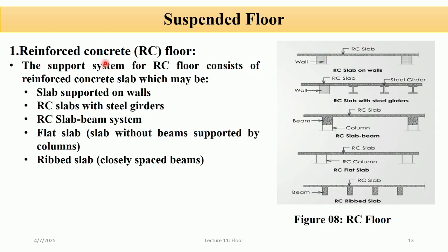Reinforced concrete floor. The support system for RC floors consists of a reinforced concrete slab, which may be a slab supported on walls. The RC slab in this case rests directly on the load-bearing wall. It is common in traditional residential buildings with no beams or columns. Load from the slab is transferred to the walls, then to the foundation.